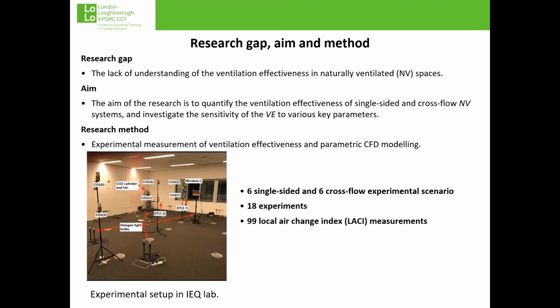In the IEQ laboratory, 6 single-sided and 6 cross-wall experimental scenarios were tested by 18 experiments and 99 local air change index measurements. Local air change index, or LACI, is a metric to quantify the local ventilation effectiveness, and it is the ratio of the age of air at exhaust to the age of air at the measurement point.